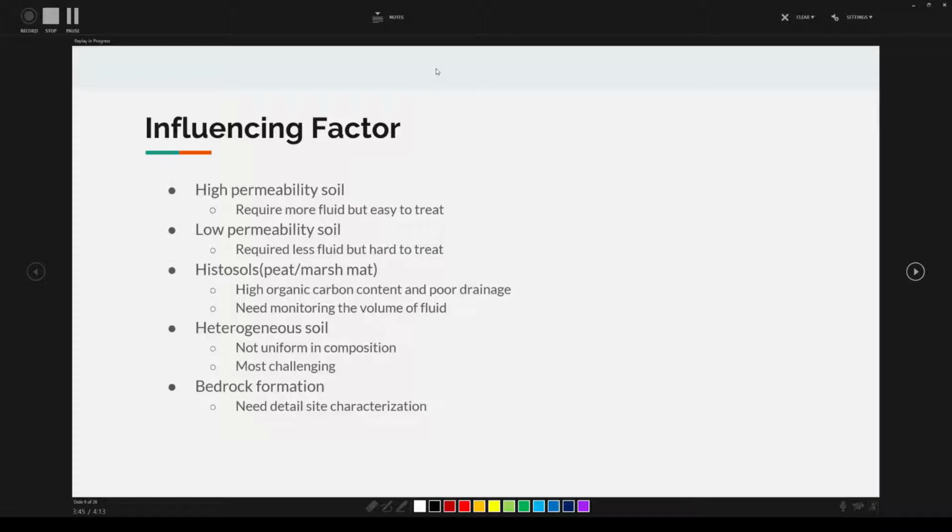The investigators remind us that in sedimentary rock formations, contaminant mass may be primarily held within the low permeability rock matrix. As opposed to the local fracture system, injection volume and extent of influence will vary significantly based on the specific bedrock formation.